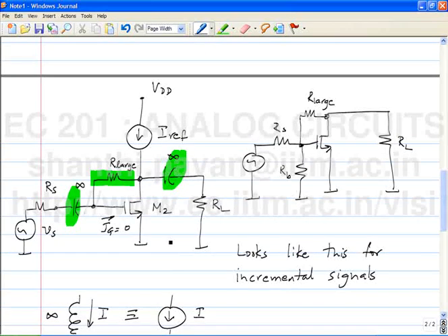Where do you think you'll be able to swing larger? The gain is the same in both cases. If R large is sufficiently large, the gain is the same in both cases. Okay? Do we have any? I mean, when we wanted to maximize swing, what did we do? Okay, why is the swing constrained? What determines the largest amplitude of the input sine wave we can put in before the output starts to clip?